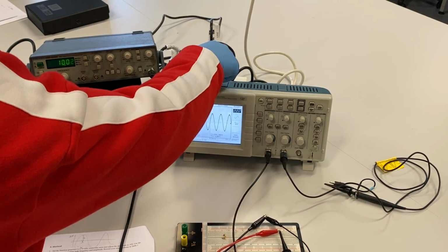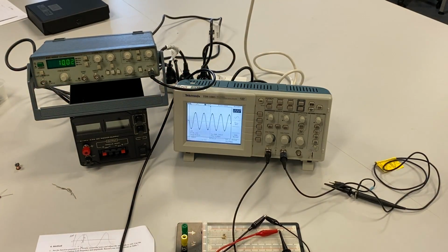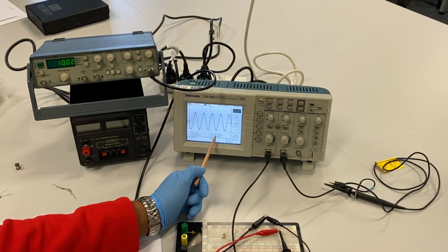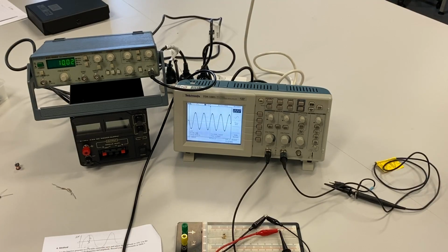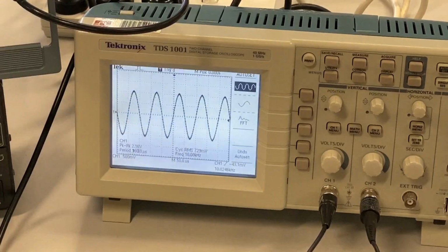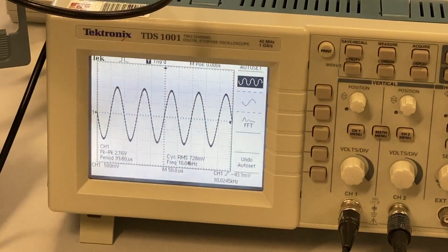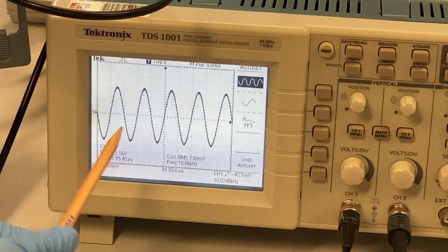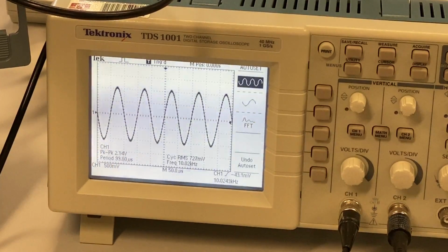Okay, just make sure this cable does not block your view. So we have that output signal, a sinusoidal signal coming in from there. The oscilloscope gives us the frequency. It's showing us 10.03 kilohertz, right? Maybe you cannot see this. Let me try. There we go. It's showing 10.03 kilohertz. But the peak-to-peak voltage at this instant is only 2.16 volts, and we need this to be 20 volts peak-to-peak.